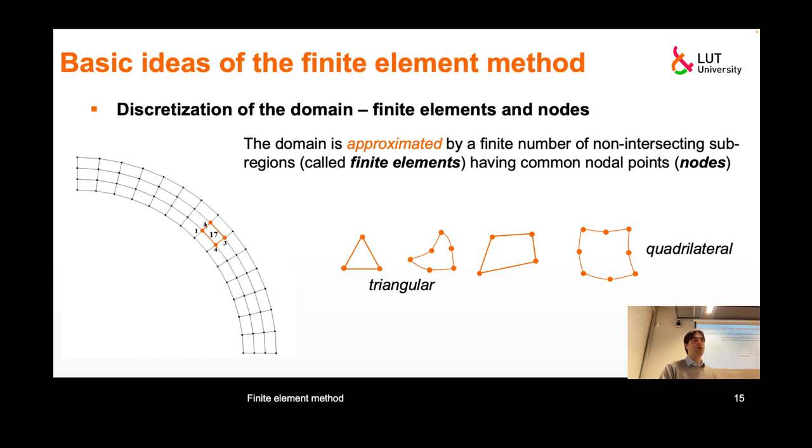So what kind of shape might those elements have? What is in my picture is kind of quadrilateral elements with straight boundaries. But it might be something different. Talking about straight boundaries, it might be triangle subdomains. So we can easily divide this volume or this domain into subdomains of triangular shape, keeping the same concept that they share boundaries, they share nodes. It's possible, why not?